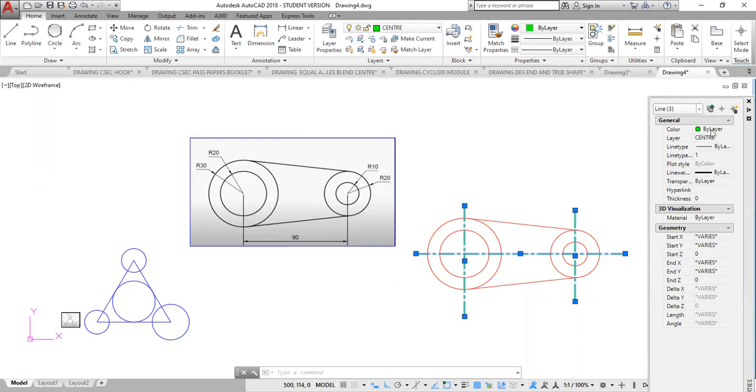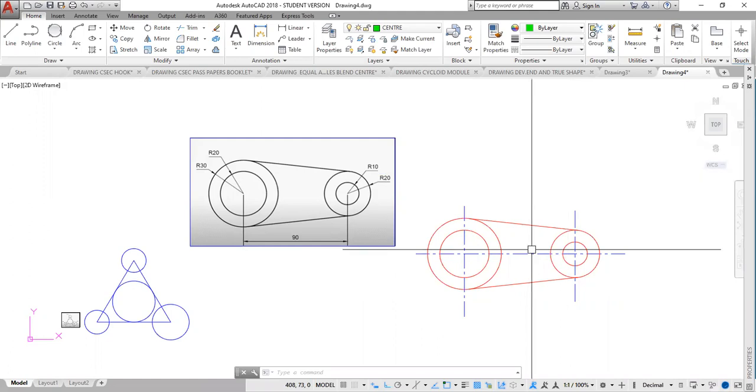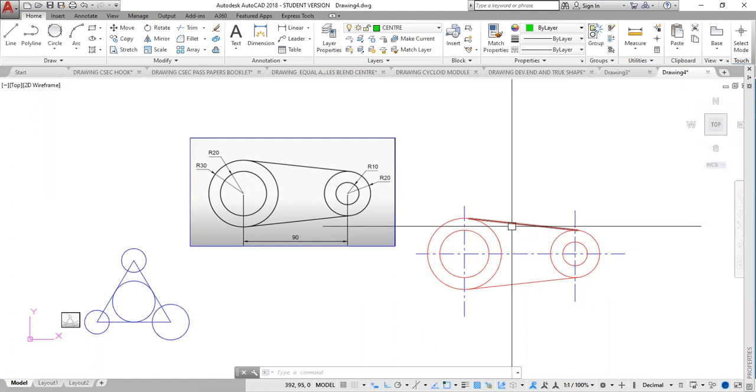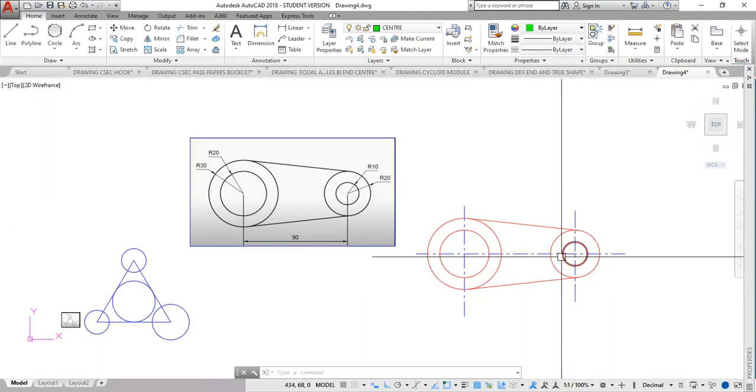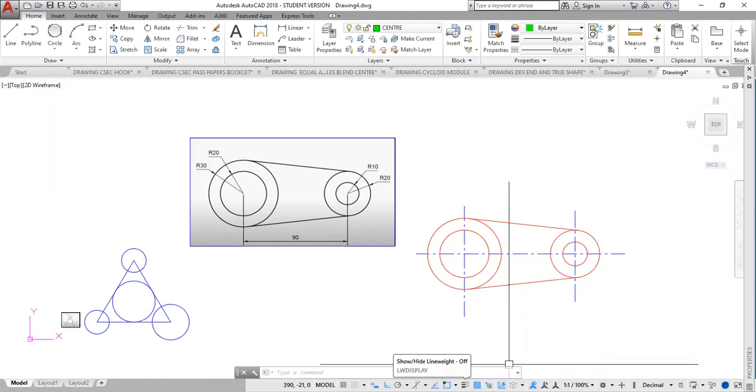I could change the color from here, from green. So I first left click onto this to enable the drop down option. Then I click here, and from here I could choose whatever color I want that to be. I could let that be blue. I think it's a nice color. Escape. Now, I could make these line weight thickness visible by clicking this icon, line weight thickness, yeah? And those lines will be visible, all right?